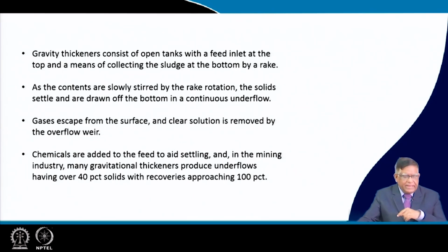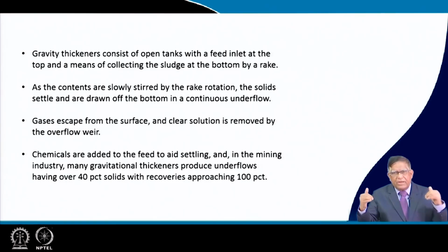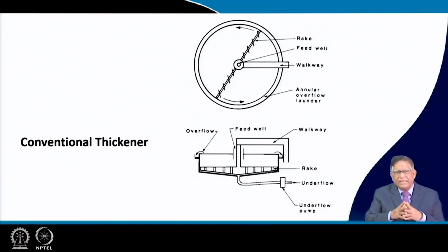Now, there could be gases associated with it, so for making them escape, we will have to give some provisions. Sometimes you may need to do stirring also, and if a lot of sludge has come over there, the evacuation may not take place properly. So there you can use a scraper and others, so that you can scrape down the sludge and put it over there. A lot of other engineering arrangements can be made over there.